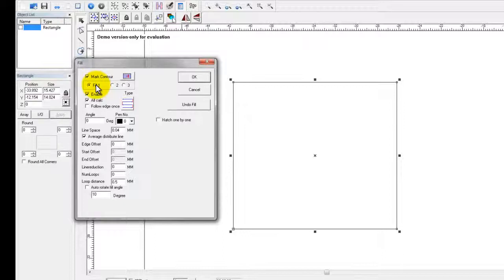If you reference our laser settings guide, you will see that the fill is very important in combination with the proper settings. In other words, if I'm trying to achieve a specific type of mark on a material, let's say what we call a black annealed mark, which is a very jet black surface mark on a piece of stainless or titanium, I'm going to use specific laser settings in order to obtain that mark.